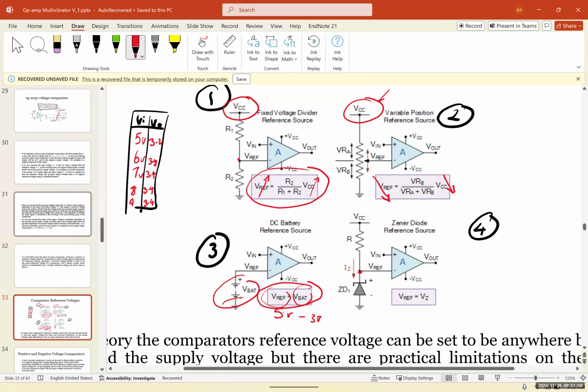So for example, if you have a proximity or an obstacle sensor on your garage, you don't want that obstacle sensor to change when your voltage is changing. And same thing for a dusk to dawn. Imagine that when the battery drops, now it's keeping the light on during the day or keeping it off during the night because the reference voltage has shifted.